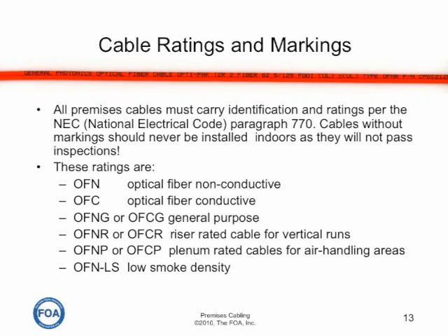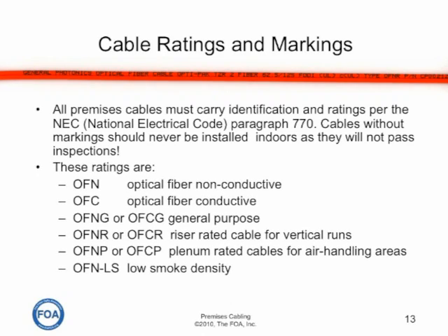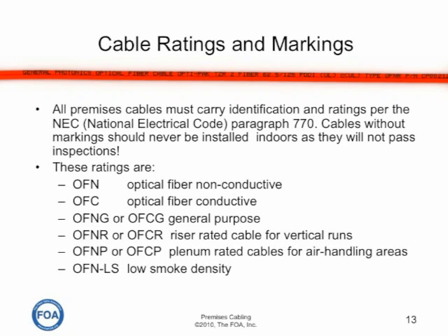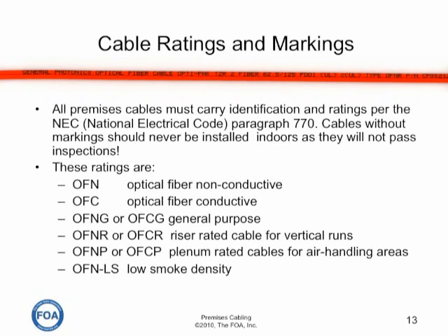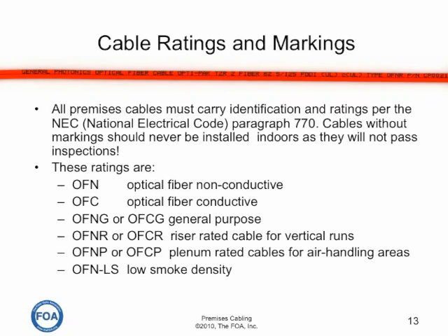Inspecting fiber optic cable is a very questionable subject. Most electrical inspectors are not aware of checking fiber optic installations for anything other than ensuring the cable is marked for flammability, although they are getting more and more involved in looking at things like installations in a neat and workmanlike manner and ensuring that all cable penetrations of firewalls are properly fire stopped.